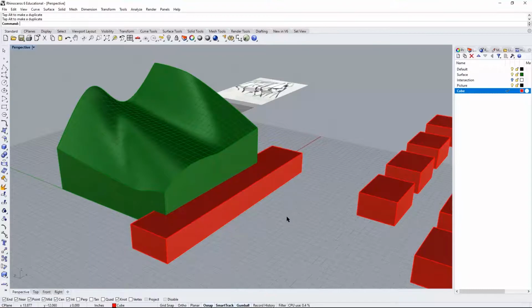So what we're going to do is when we have poly surfaces to subtract from each other, we can use Boolean options. And over here, there's the Boolean Union. That's going to put both of these objects together. There's Boolean Difference, which is a subtraction. So one will subtract from the other one. There's an intersection. So wherever those two intersect, that will be the piece that remains. And Boolean Split will just split it into its constituent parts. And these three are primarily the most used Boolean options.